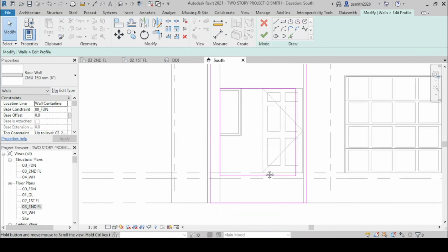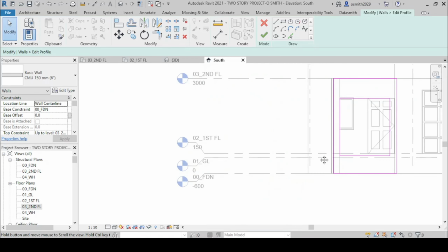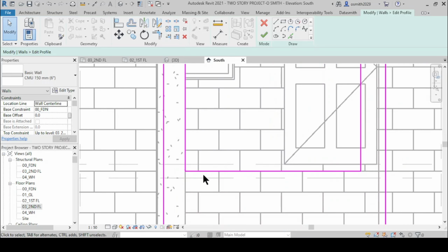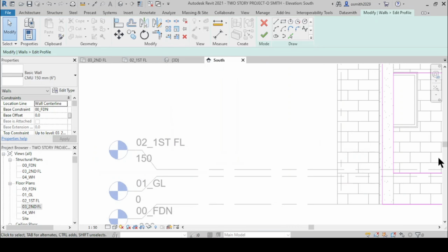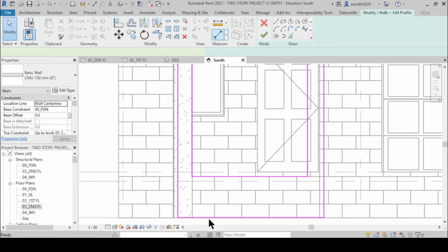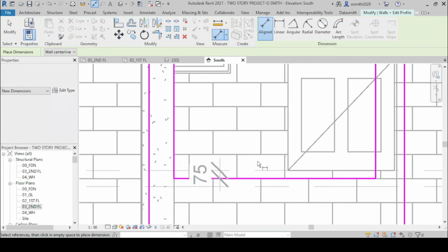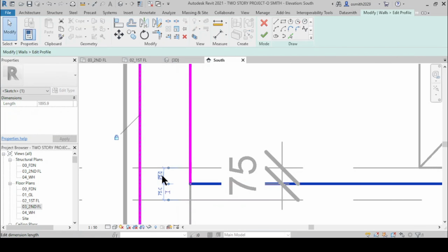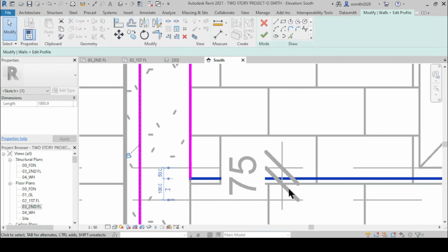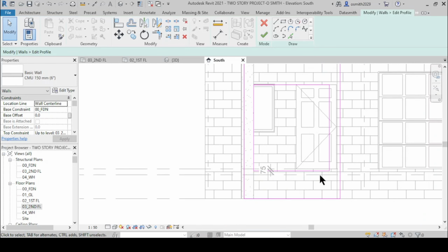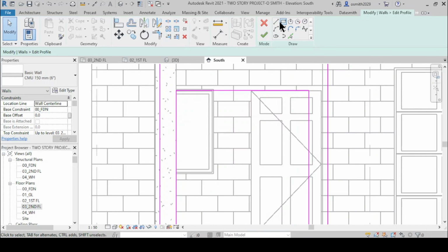After I draw that box, I'm just going to edit things. I want the lower end here to be 2 inches lower than my first floor level, so I'm just going to adjust that by measuring, and then I click the line. It's supposed to be 50 millimeters. There we go. That's the same thing as 2 inches, right? And from each edge here, I need it to be 300 millimeters away.